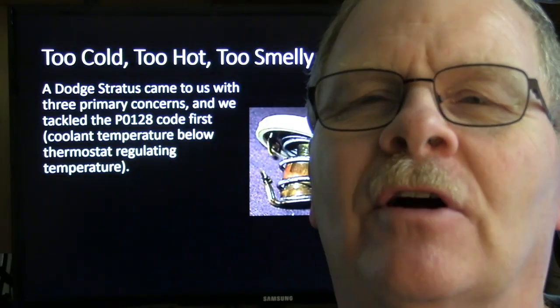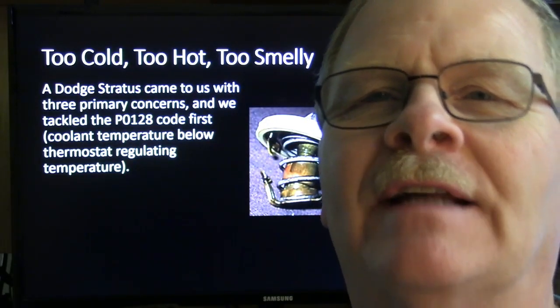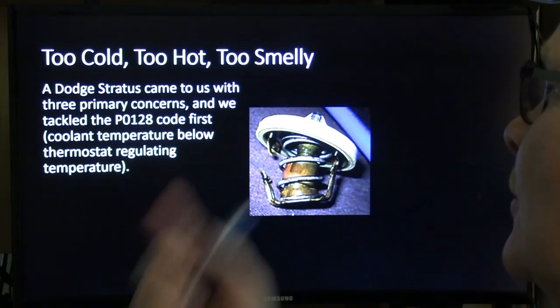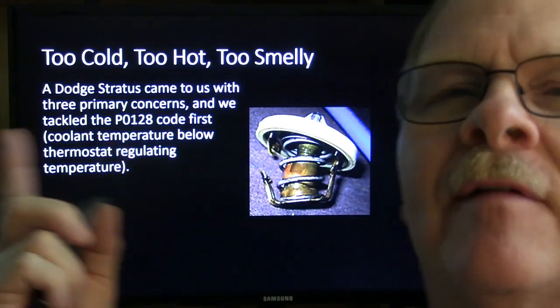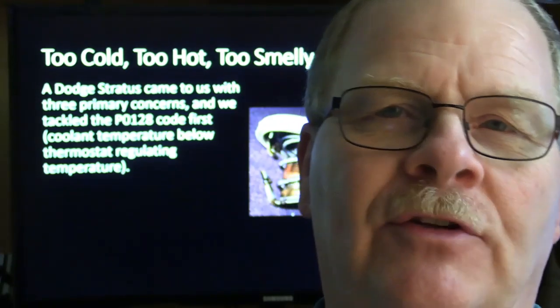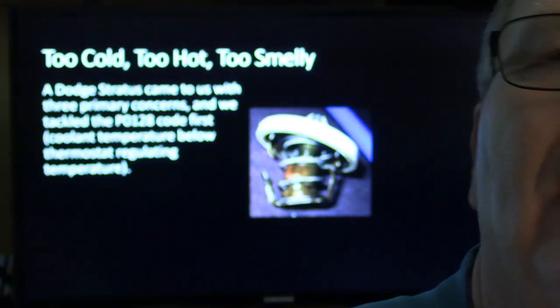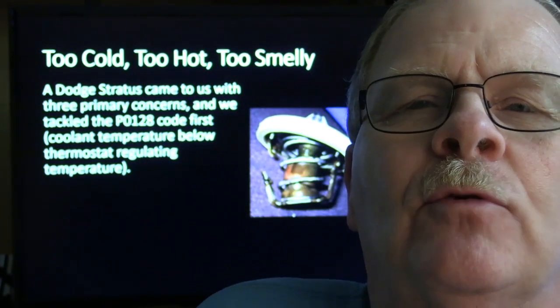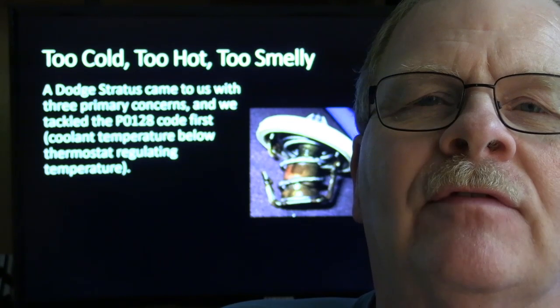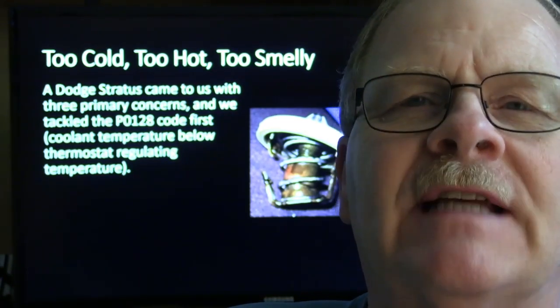But anyway, we're going to start out talking about this Dodge Stratus, and it came in with three primary concerns. One of them was a P0128. Now, a P0128 and a P0125 are very similar codes, and what the P0128 and the P0125 typically both point to is the thermostat.